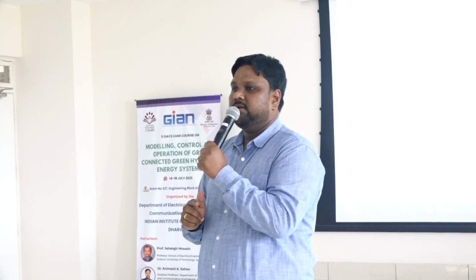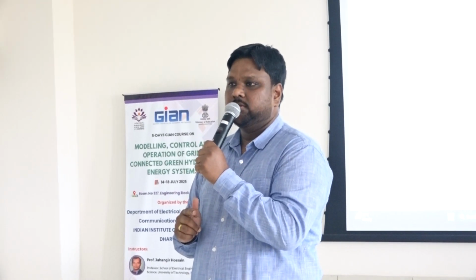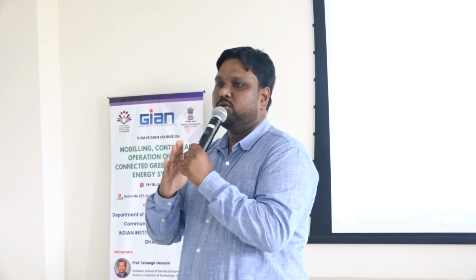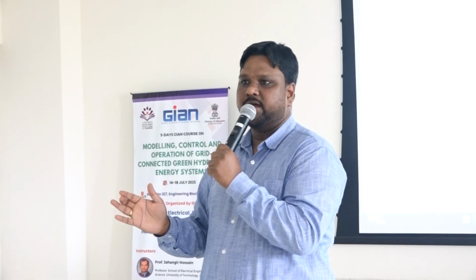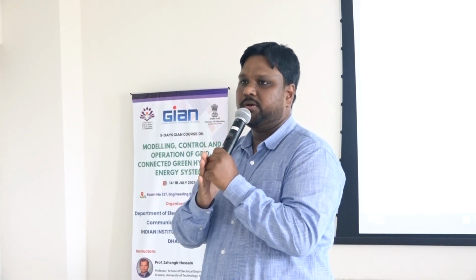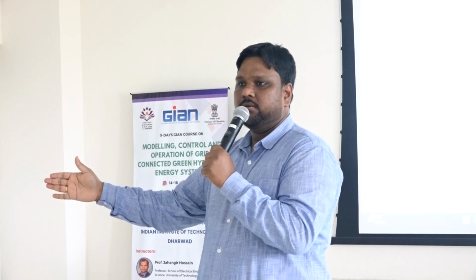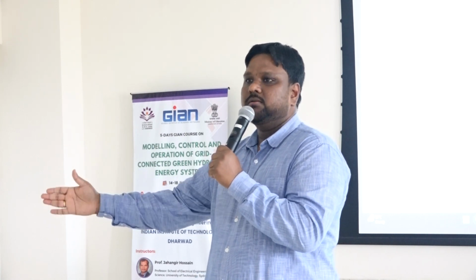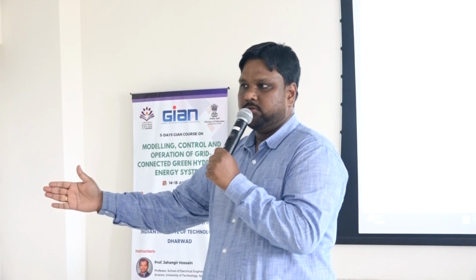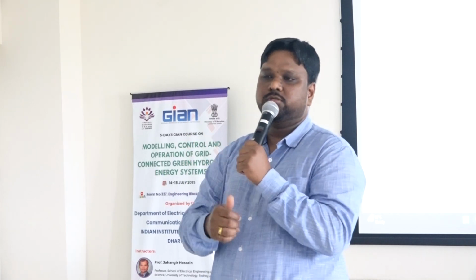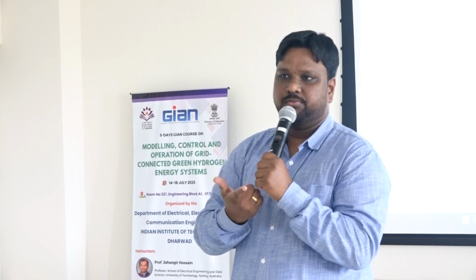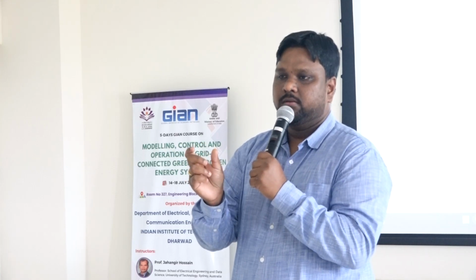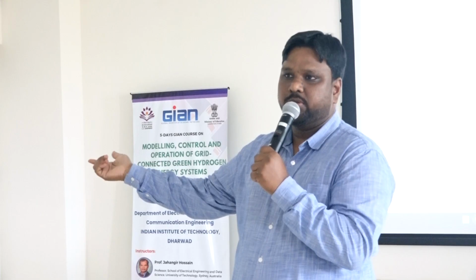I will not give the same pulse, because we are doing phase shift. So my switch number 1 and switch number 5 will have a phase shift. If I don't have phase shift, to be frank, switch number 1 signal should go directly to switch number 5. But I don't want to turn them on together. So the pulse I am giving to switch number 1, I will give a little bit of phase shift phi, and that I will give to switch number 5.